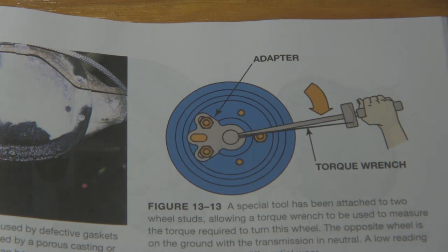It's fairly straightforward. Usually you're talking like 35, as the book says, 35 to 40 foot-pounds of rotational force. Above is bad, below is bad, and if you find something outside of that, depending on what the customer concern is, you're going to be tearing down the axle at that point to replace those components. And then, again, that could have been done because somebody did not use the proper friction modifiers the last time it was serviced, or maybe the customer just really drives the vehicle hard, they hot rod it, and they've burnt up the limited slip components.